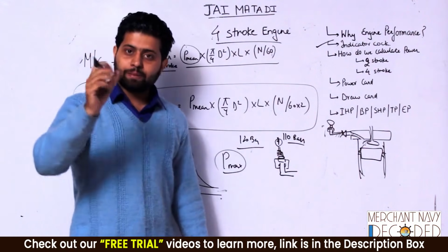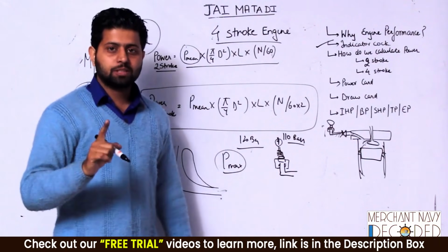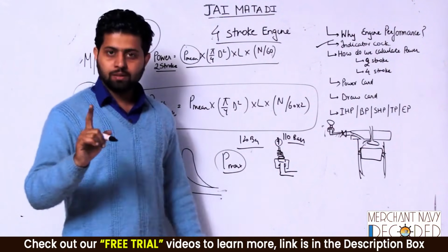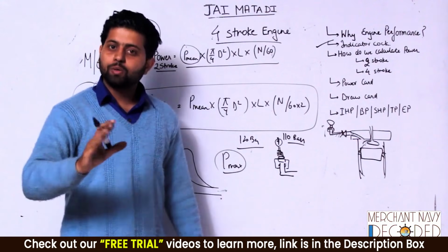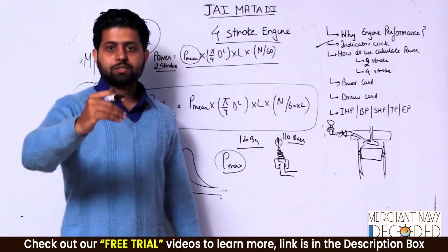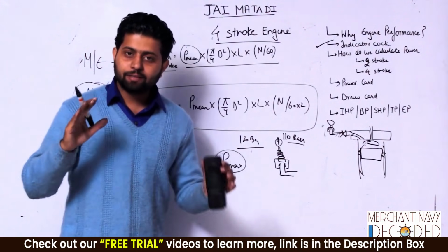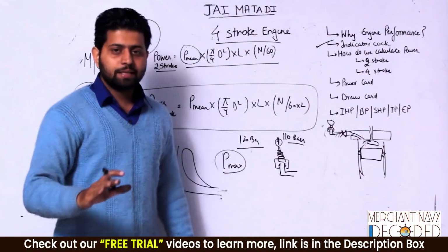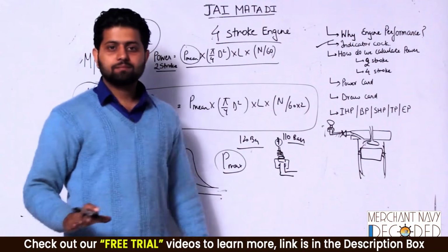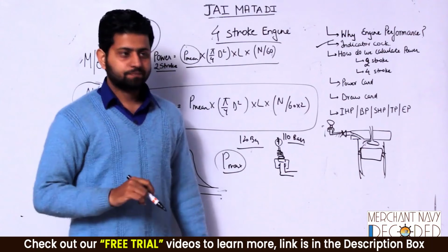So in case of generators, we run it at 85% load, say, and we get all the P max, that is the maximum pressure being generated inside, and we know one thing, if maximum pressure generated inside is the same, that means your P compression is also going to be the same. And you see all the units, exhaust temperatures, cooling water temperatures, lube oil pressures, and then you get a very good idea that my engine is running in good shape. Clear, guys? This is important. Now,